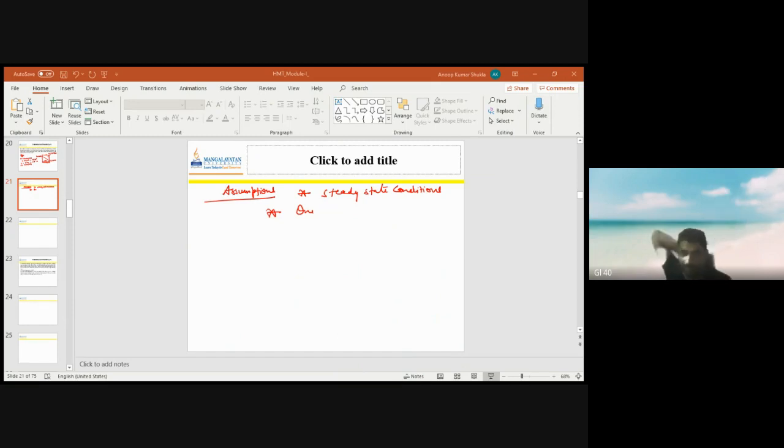So this will be the profile of temperature from top to bottom. The first layer of fluid that is directly in contact with the hot plate will be the most heated. It will be at the same temperature as the plate, and gradually the temperature decreases. So the rate of heat transfer Q upon A is directly proportional to Ts minus T infinity.